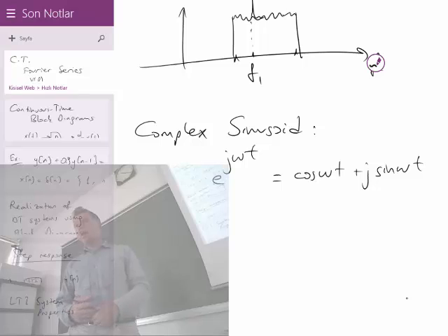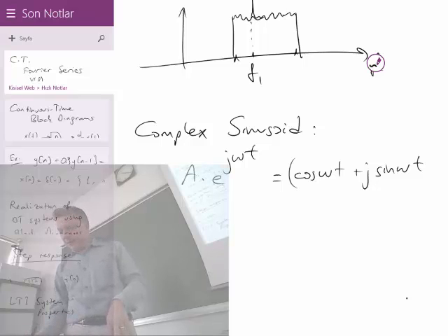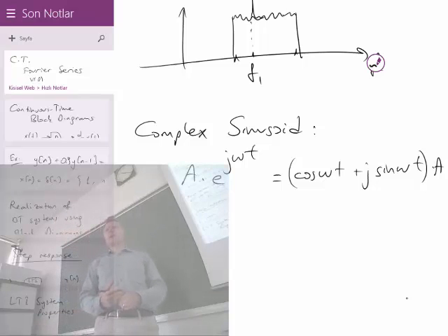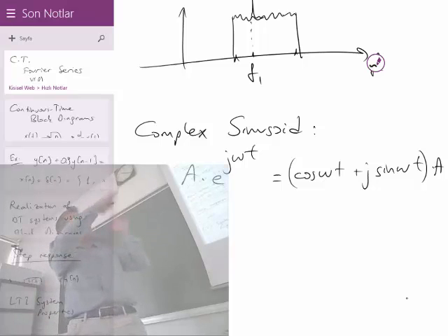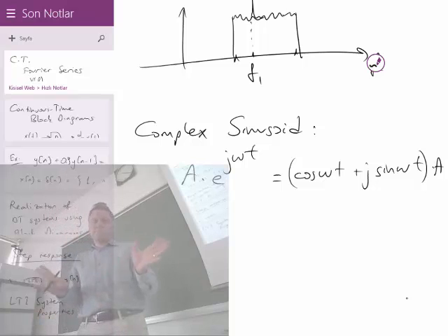So it has a real part and a complex part. Both of them are sinusoids, and overall that corresponds to a complex sinusoid. So the representation will be the omega axis, and the magnitudes will correspond to the magnitude of this thing, A times e to the j omega t, for example. So A will be the magnitude at the frequency omega. And this A could also be complex, by the way. If it has both real and imaginary parts, you have to multiply the real and imaginary using the cross multiplications for expanding into cosines and sines. You don't need to expand them in general.